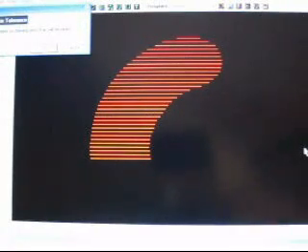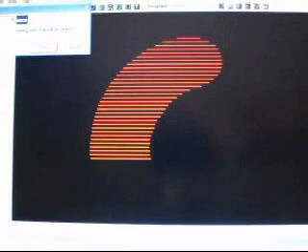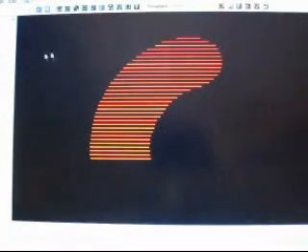I mean, you could join it at 0 if you'd like, but I'm not too concerned about it, so I'm going to join them at 1/1000 of an inch. Okay, press enter, and now you will see they are all polylines. See, if I step through the list on that layer, they've all been joined. Okay, and this is important that you do this.